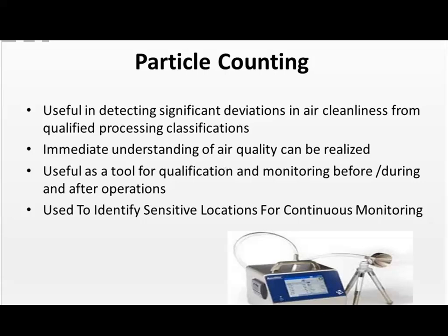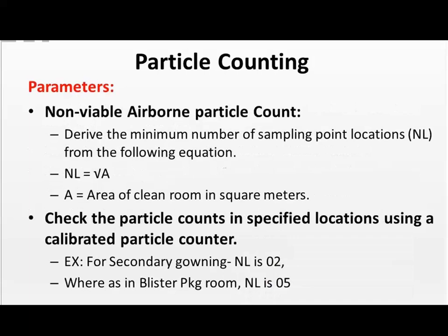And in the slide here, there's a picture of a laser particle counter, and there are a few different types of laser particle counters, but the size of micron that they're looking at is 0.5. On the screen, you're going to see a lot of different sizes of particles, but your criteria and specifications are going to be based on your 0.5 microns.